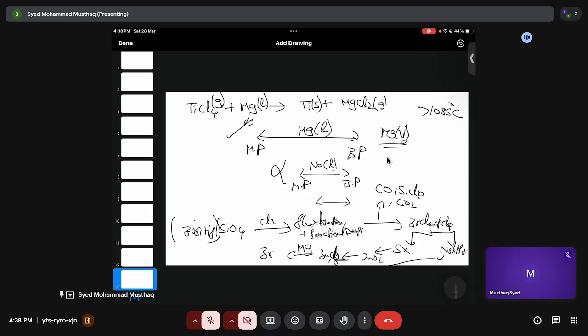Same, you take the hafnium, either you do the solvent extraction or you do the chloride distillation, you will have a hafnium chloride. And from hafnium chloride you can go again two ways. Either you can go same, the magnesium one, or you can do the molten salt electrolysis. So if you do the magnesium part, you will end up with sponge, and if you do the molten salt electrolysis, you will end up with crystals. That's it. There is no extra thing.